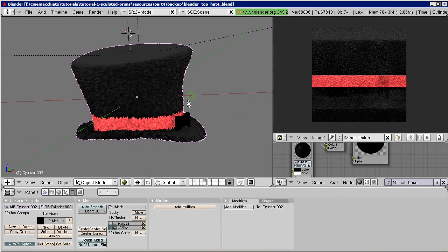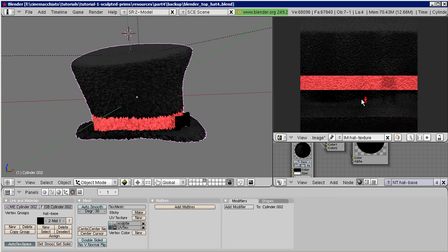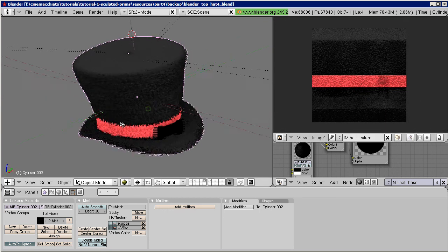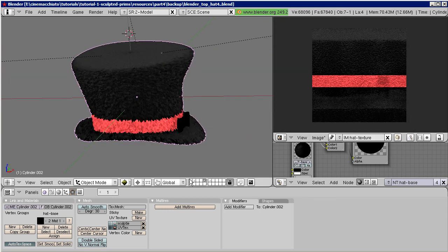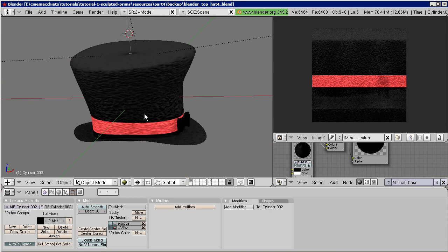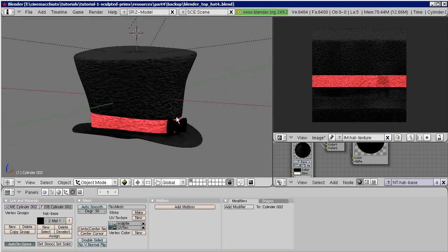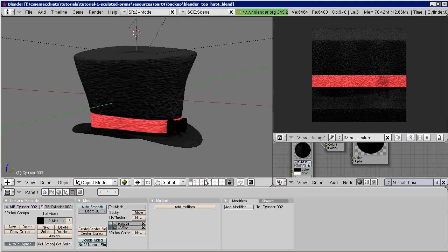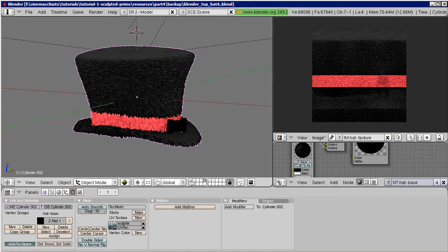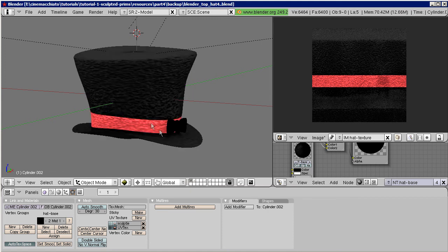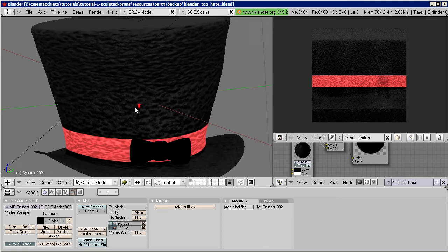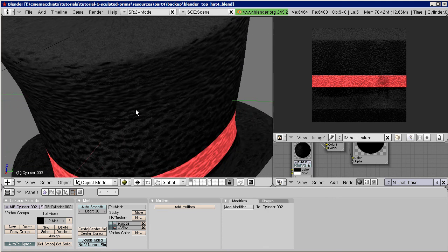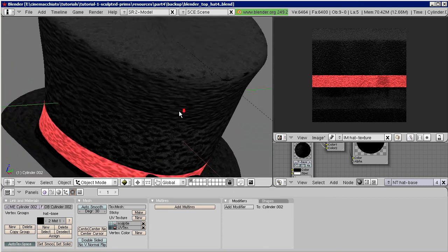Now the texture contains the light effects of the noisy surface. Now switch to layer 1, and see how the same texture looks on the low poly hat. So the low poly hat looks similar to the high poly model, at least up to a certain extent. You see that you can at least in principle use the texture to add some fine details to your object without actually adding more vertices and faces to your mesh.